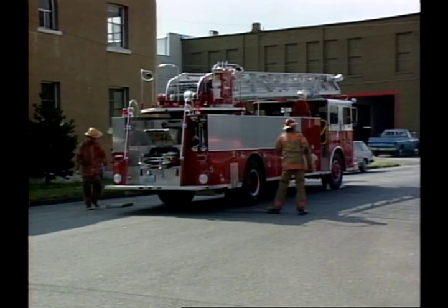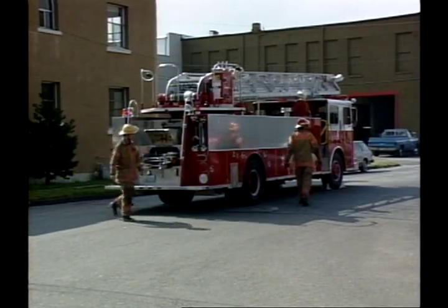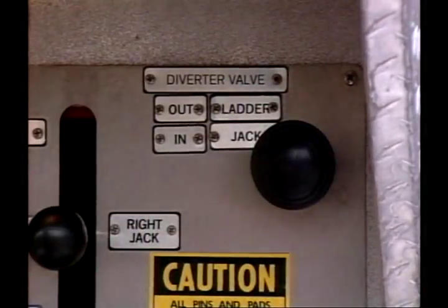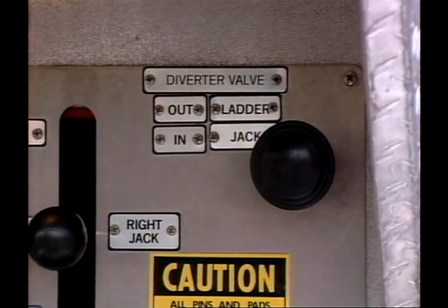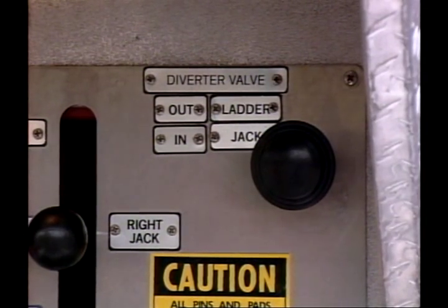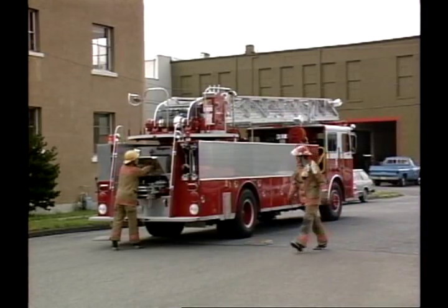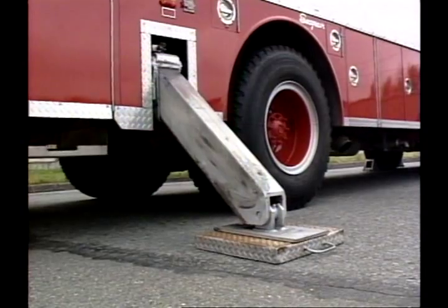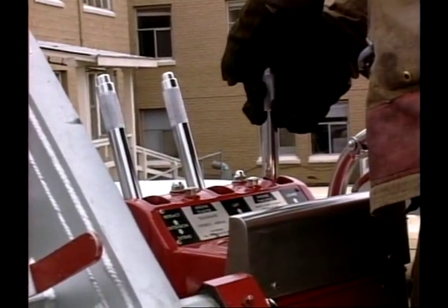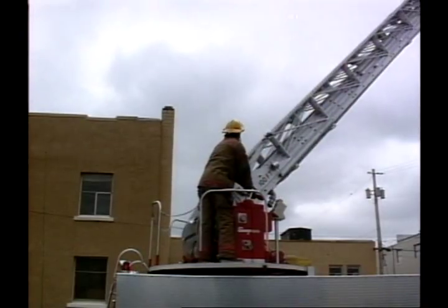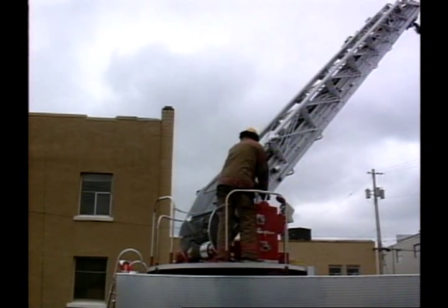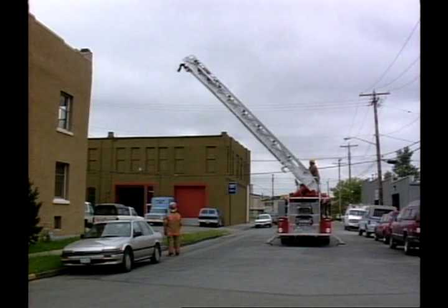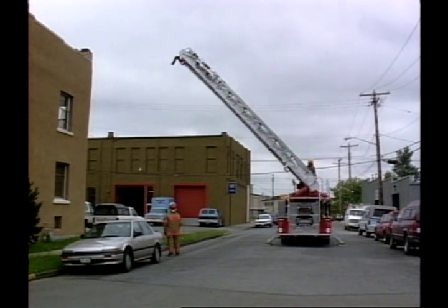Valves are used to start, stop, regulate, and direct the flow of oil within the system. One valve that is especially important is the selector valve, also known as the transfer or diverter valve. The selector valve is a three-way valve that directs the oil into either the stabilizer controls or into the aerial device controls. By blocking oil flow to the system that is not being used, the selector valve acts as an interlock to keep the stabilizers and aerial device systems from operating at the same time.